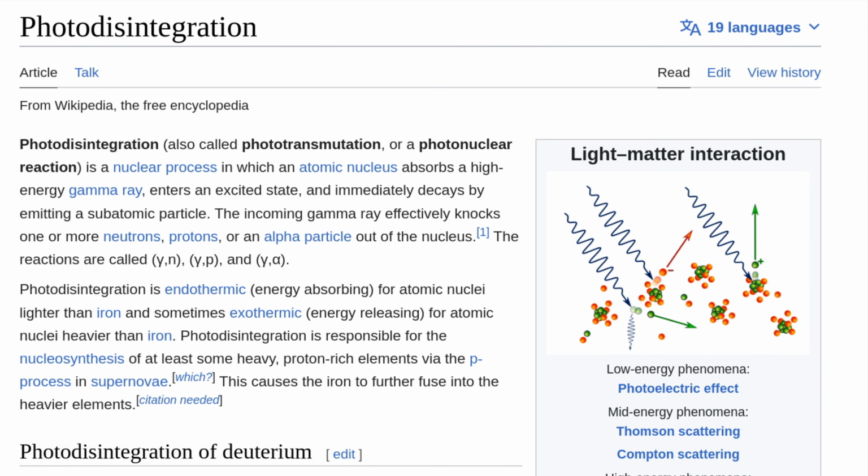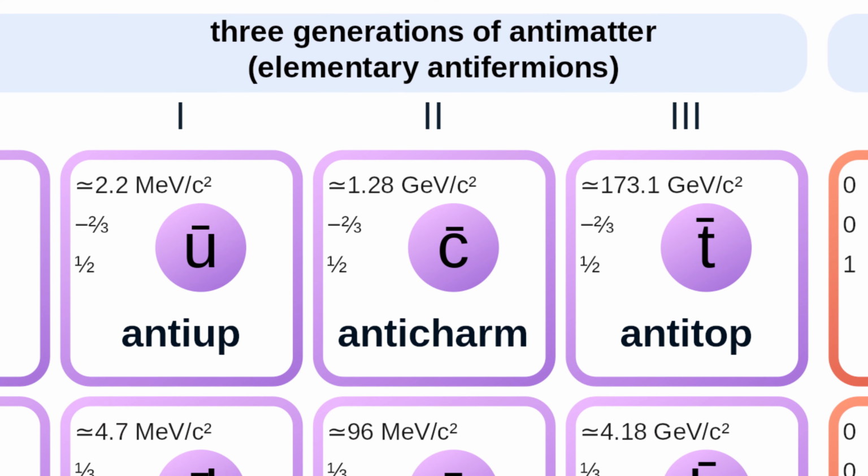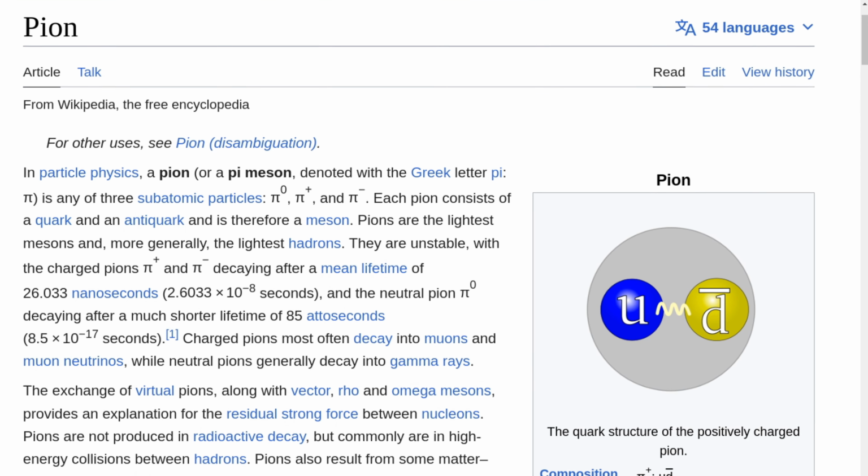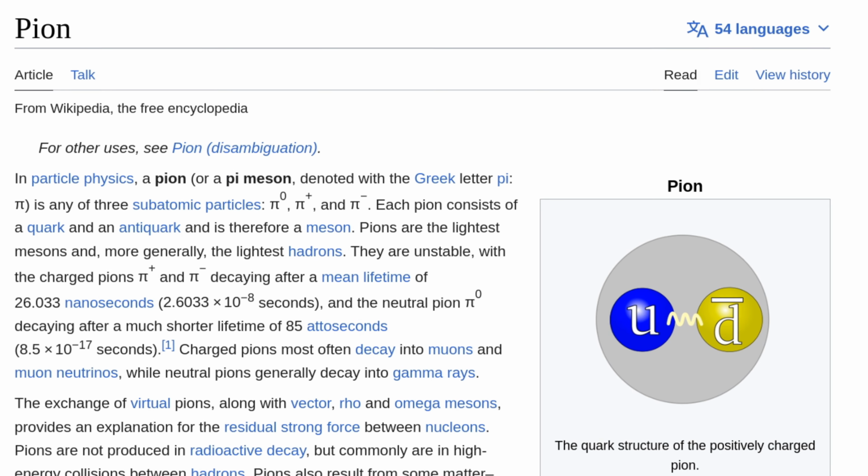High energy electrons could be problematic if they become embedded and accumulate inside the chip, or if they're energetic enough to create secondary particles. Low energy electrons would be less problematic, and their effect would be similar to that of thermal noise. High energy photons, like gamma rays or X-rays, are able to catalyze nuclear reactions, so they could be another source of exotic secondary particles. High energy photons are a form of ionizing radiation, so they would have the ability to strip electrons off of atoms in the chip. This could obviously disrupt electrical charge states within the chip. This isn't even an exhaustive list of particle interactions either. There's also antimatter particles and all sorts of exotic, short-lived, intermediary particles that I won't even talk about.